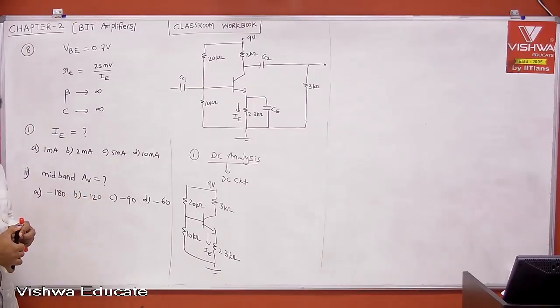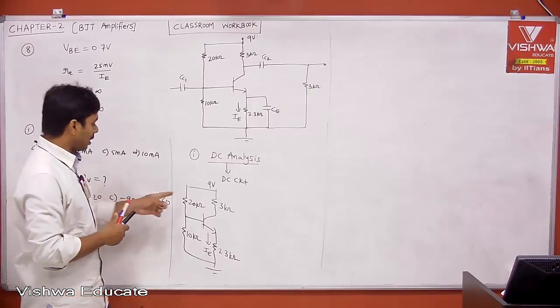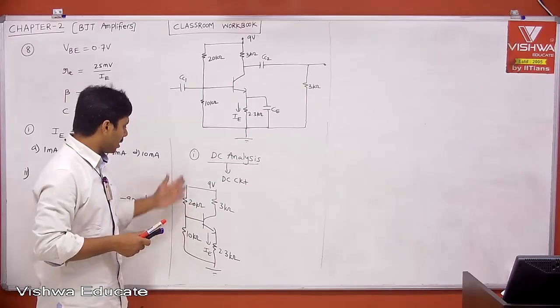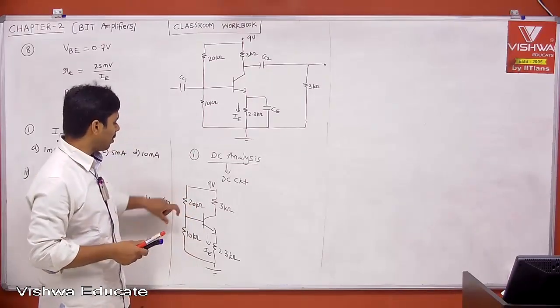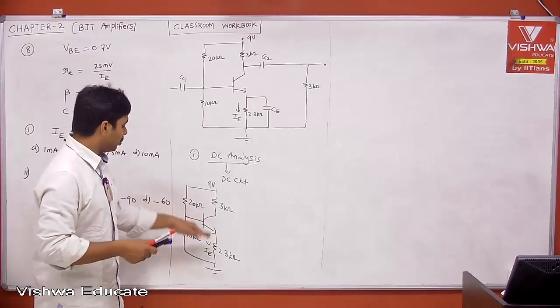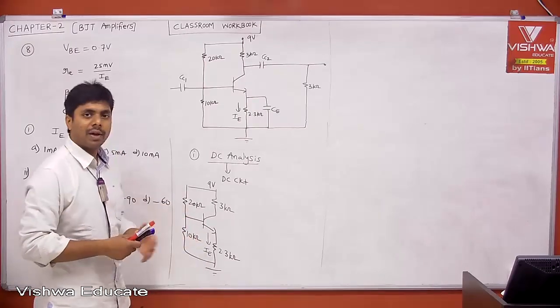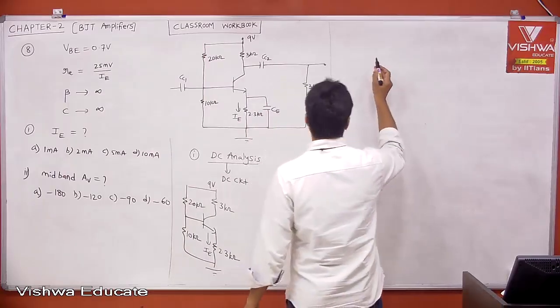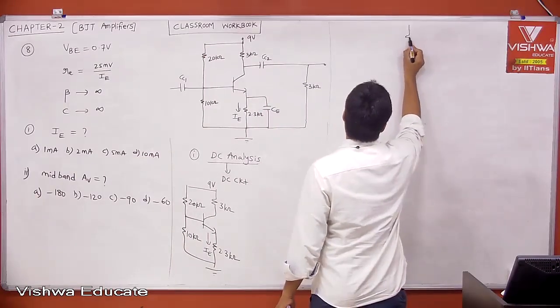We got to know the DC circuit, but you remember I told you, right? R1, R2. If you want to solve a self-bias circuit, just apply Thevenin's theorem. Then you will get VThevenin, RThevenin. Then apply input loop KVL. Then you can find IE. That is straightforward. Therefore, tell me, applying Thevenin's theorem, what do you get?